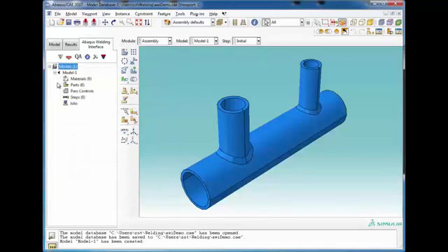Okay, so we've just initialized a model, and then for that given model, we're going to have to go through these 5 steps. We're going to choose which materials we're going to use. We're going to select the parts and the welds and the weld beads. We're going to set some pass controls, and then inside here is where we create the Abaqus steps and define the passes that are being laid down. And then finally, the last step is just letting Abaqus, or the welding interface, generate everything it needs to do.